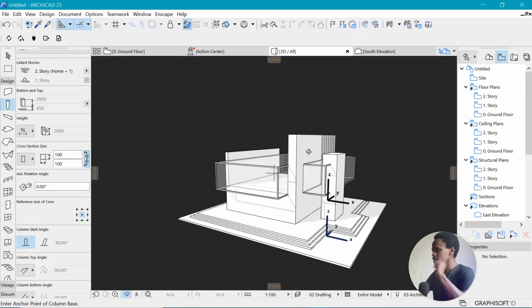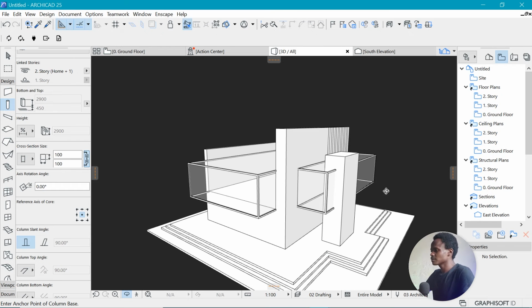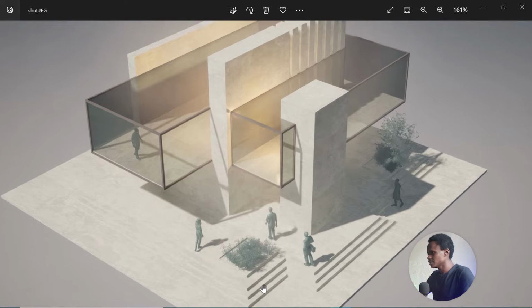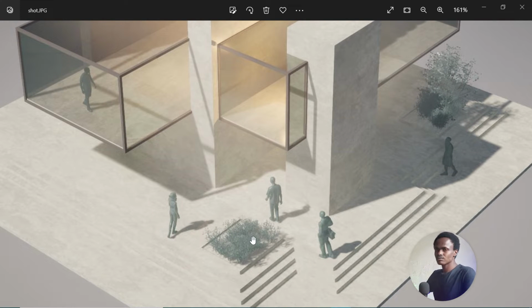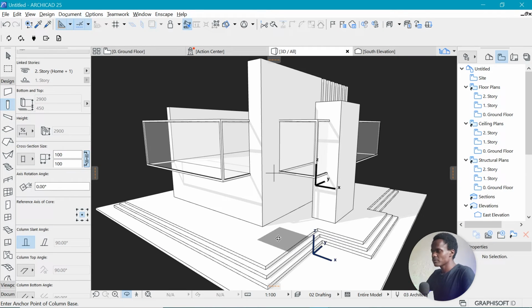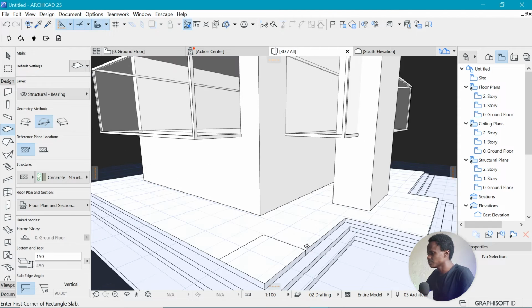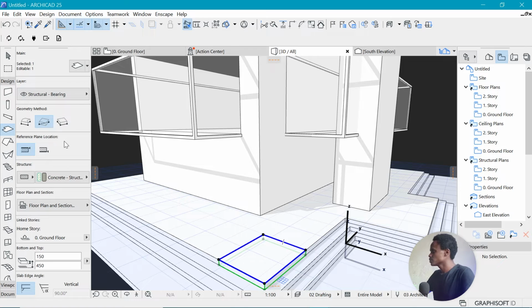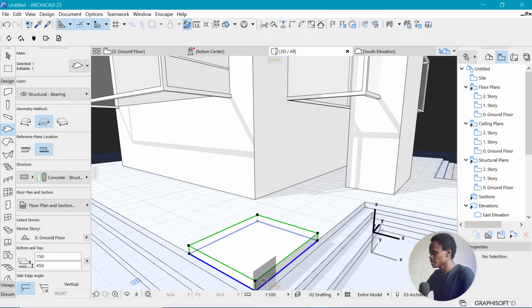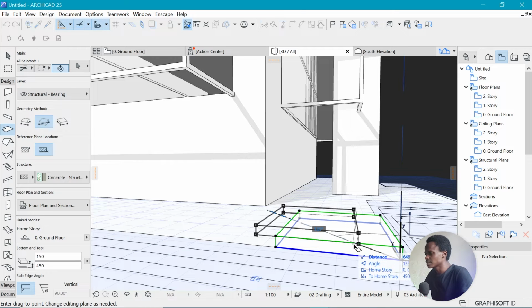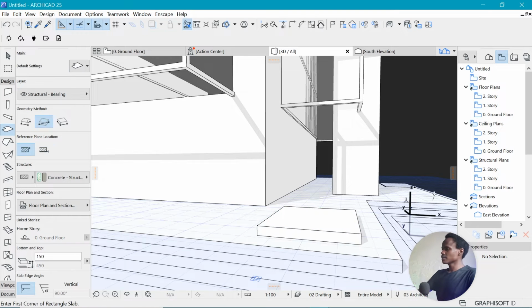But before we go, we also need somewhere to put our gardening or the plants. So you can see we have some plants here and here, and we created a small planter section for them. So how do we achieve that? Well, let's just make these simple slabs. I'm going to make it, yeah, that size will do, and making sure that I change the reference to all the way up. I meant across the surface, so we can do that with that reference.